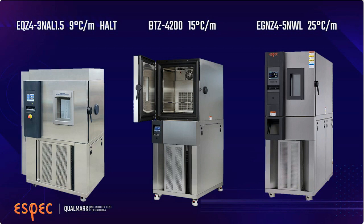There's the EQZ4, which is a small HALT system with repetitive shock and refrigerated cooling. 9 degree per minute ramp rates are possible, but with liquid nitrogen, you can get full HALT performance. There's the BTZ 4200, which has 3 horsepower refrigeration and onboard air cooling, and 15 degrees per minute is possible with this. There's also the EGN-Z4 chamber, which is the same size, but has 5 horsepower refrigeration that does require water cooling, but you get 25 degree per minute ramping.